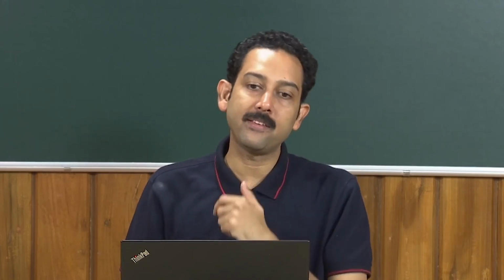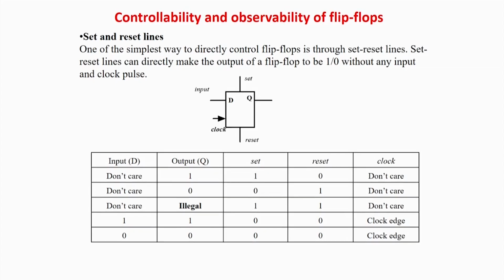The problem compared to combinational circuit is that you require more number of test patterns to test a single stuck-at fault. That is where optimization is again coming into picture. Even if it is a very small level circuit where you have 100 faults, to test a single fault, if you require 10 or 20 patterns, to test 100 faults it will be in the level of 1000 patterns, which is not at all possible even for a medium scale integration circuit. Forget about NOC and SOC.